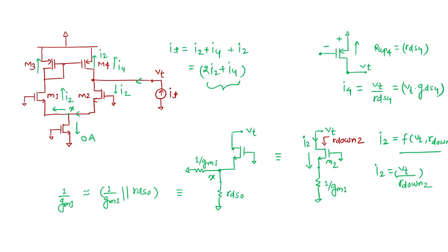Later, when we will be analyzing the other things, like the zero at the mirror terminal and after that the pole at the mirror terminal, we will see exactly how helpful this analysis is. We should have an understanding of each and every node impedance. We should not directly say that this is 1 upon gm, or that it is RDS only. Let me tell you one thing: we should always remember what exactly is happening with the current components, and after that we should proceed with the calculation. There will not be any mistake, and this is a rigorous way of analysis.